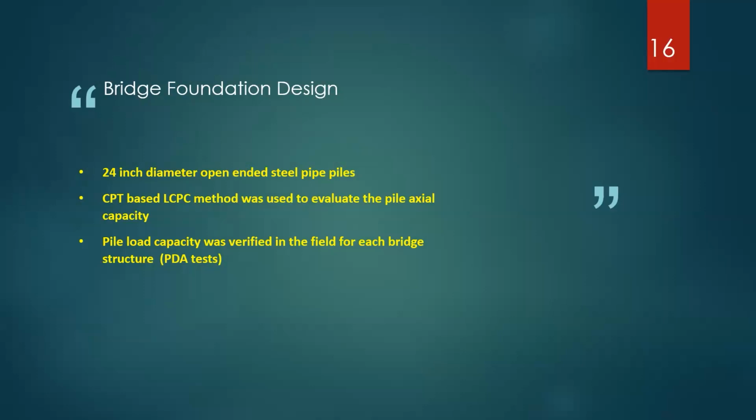And these open-ended steel pipe piles were 24-inch, and the method that we used for design was the LCPC method, which is the French method. In other words, it was used to evaluate the pile axial capacity, and the pile load capacity was also verified, which was required in this job for these types of foundations for each bridge structure, using PDA tests.